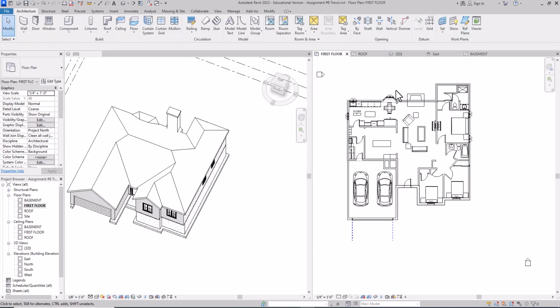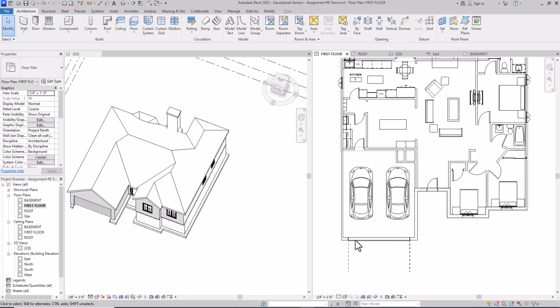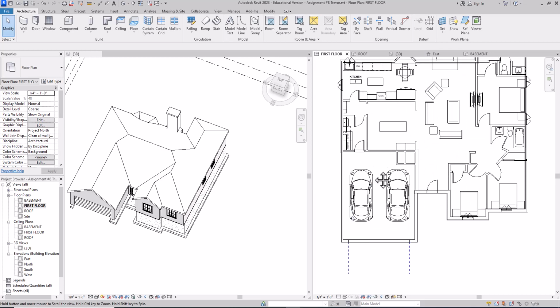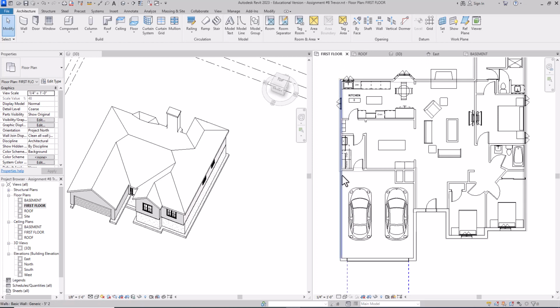Okay, so I went around the entire house, but keep in mind that the garage will be on a slab on grade, so it's not going to have its own foundation wall. Sometimes it does have a trench footing, which is shorter, and it doesn't usually have a footing on it. So let's take a look at this one first.